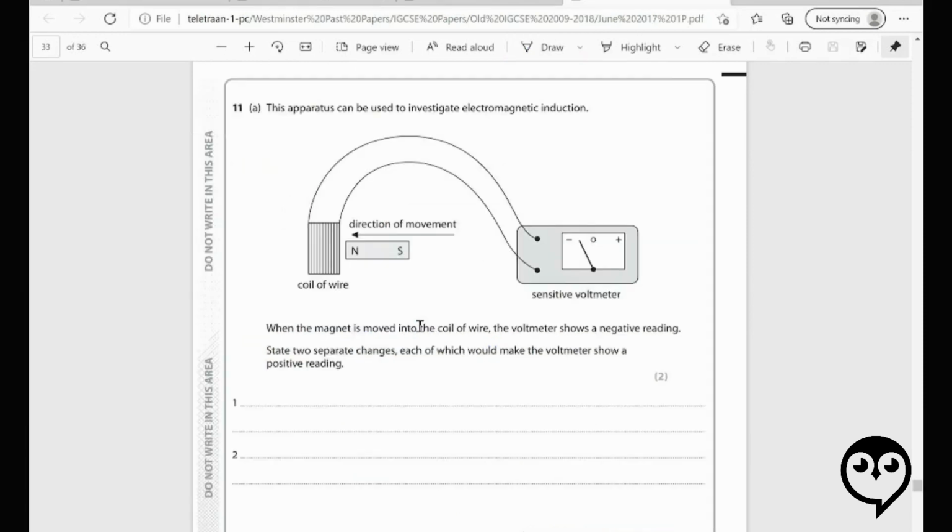Okay. All right, if we were to go back to this previous question just for a moment here, we note that we can cause an induced voltage in this coil of wire two ways. Either we move the magnet into the coil, or we could keep the magnet stationary. We could move the coil around the magnet, okay? Either way, what's happening is the magnetic flux lines, the field lines, are going to be cut by that coil, and the flux density entering that coil is going to change, all right? And we can do it one of 2 ways.